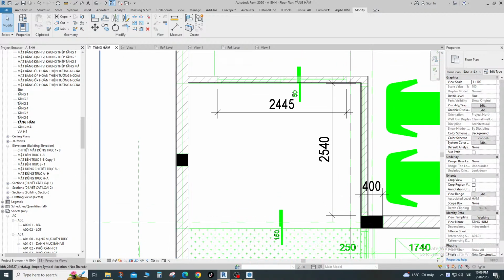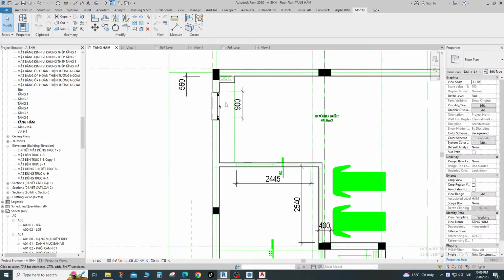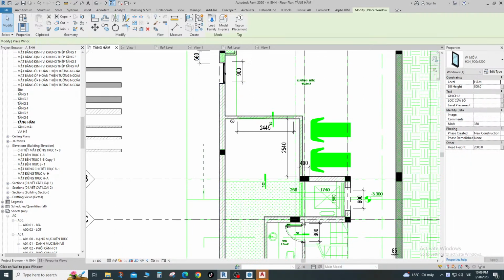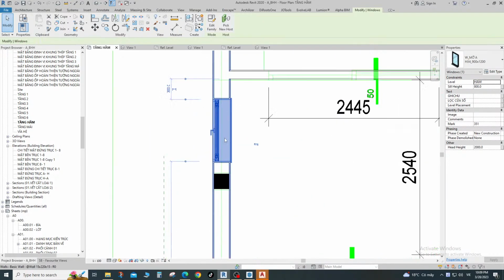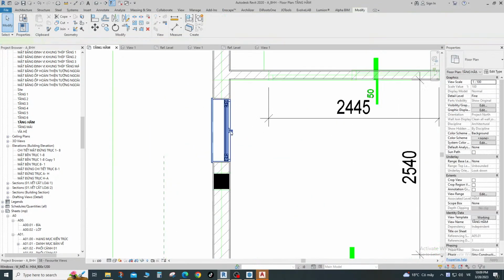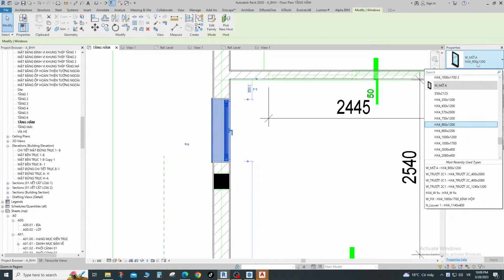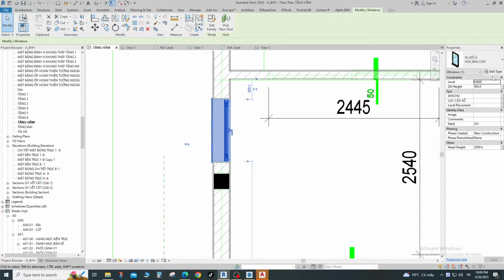Finish. And then we still need to adjust the size of landing. Let's check the dimension. That's fine. We're good. 1.5. Maybe we don't need 1.8, so we just need to move this down by 300. So Revit automatically adjusts the landing to suit these two stairs. So 5 stairs. And then what is this one? Maybe move this down by 500. And now that's all good. Finish. Go to 3D view. We have another stair.